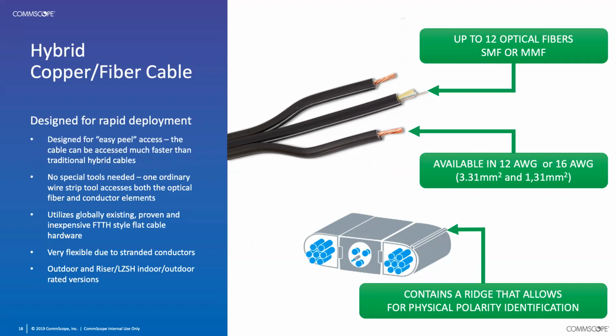And at the other end of this hybrid cable, we have basically a converter that's outdoor rated, so rated for extreme temperatures as well as inclement weather, rain, and so on. And that will terminate in a standard copper RJ45 PoE connection. So basically, it's like extending your PoE port out, up to a couple kilometers. So this is one way if you have to get a further distance than you can run with copper Ethernet, and you want to be able to provide both power and that fiber connection, this hybrid cable is a good solution for that.